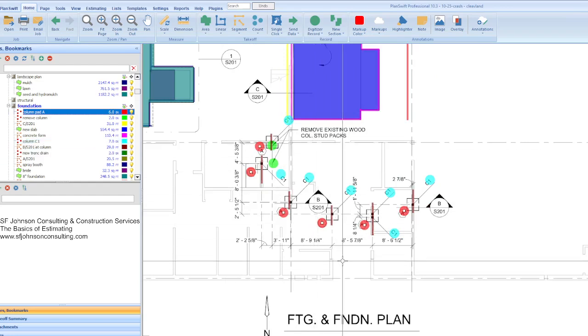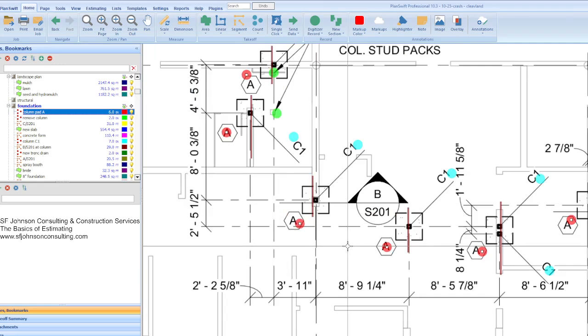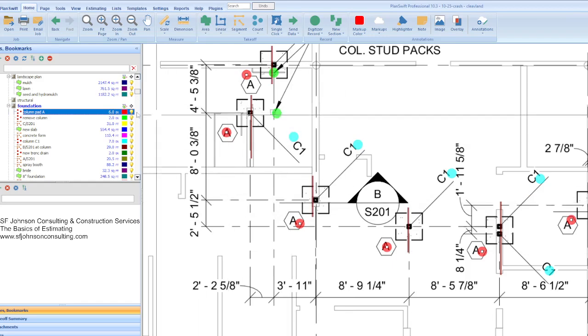And when it comes to your beams too, you have to have a good cost book to tell you, because based on the weight, it goes from 0 to 20 pounds. It's a certain amount of cost per pound. Then we go from 20 to 50 pounds. It's a certain cost. And then from 50 to 75 pounds, and I'm talking weight per linear foot, that second digit. And anything over 100 pounds per linear foot, that's like a specialty thing. There's no cost book that's going to have that information. Okay, so that's very important.